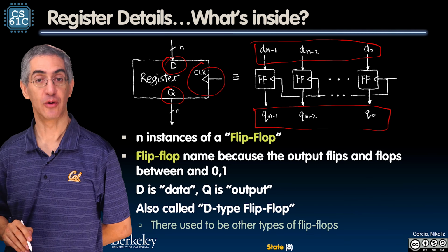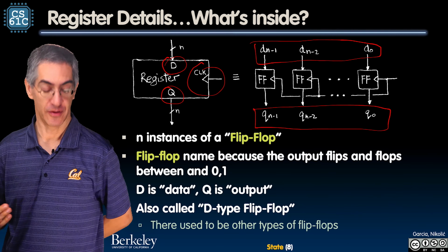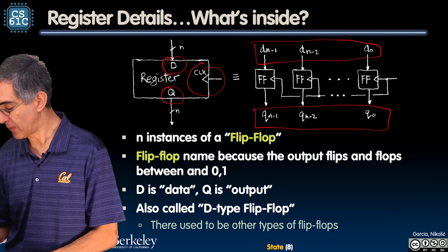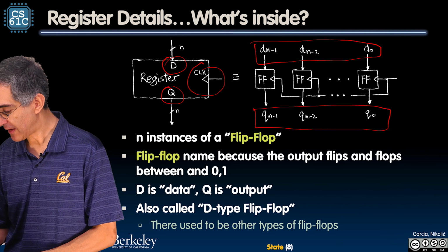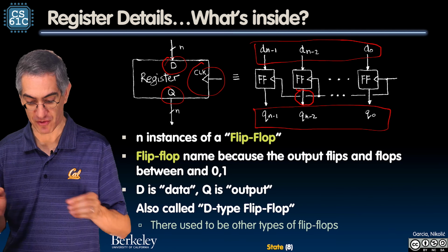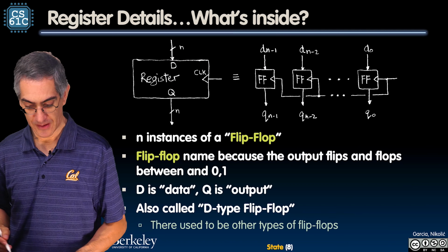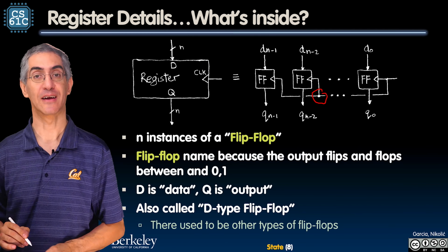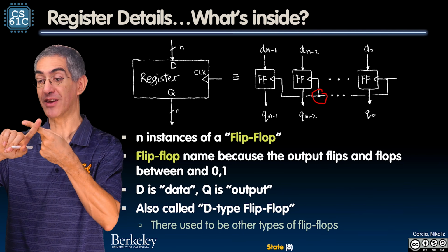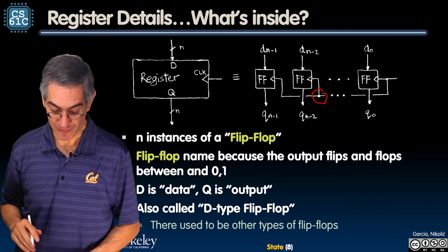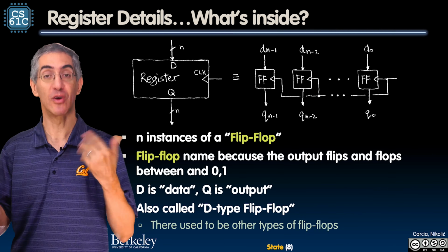This clock, which says load the register, has to be sent to all of these. And this may be the first time to show you: whenever I show a line that isn't connected, I'm going to show a gap there. That's really important. Whenever I show a line that is connected, I'm going to draw a circle there. If you ever see a line like this, it's really ambiguous. Should it have gone underneath with a gap, or should there have been a circle? We're never going to do that. We're always going to make it very clear which one we meant.